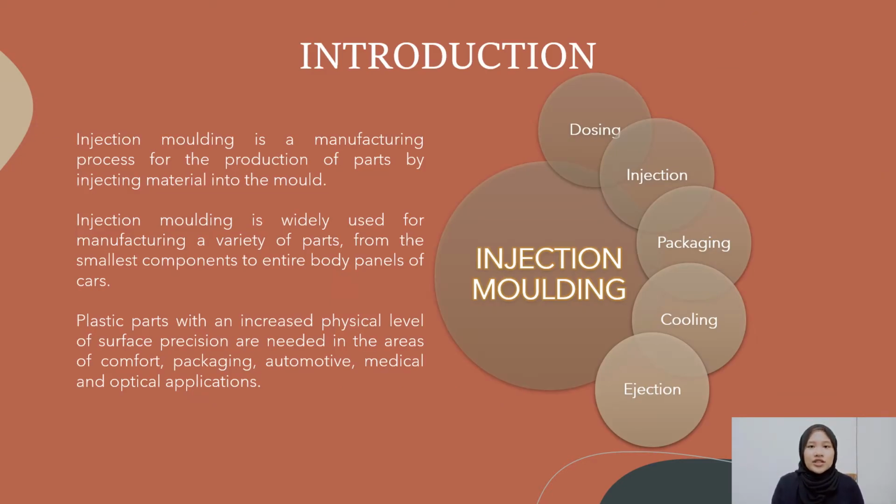What is injection molding? Injection molding is a method to obtain molded parts or products by injecting plastic materials molten by heat into a mold and then cooling and solidifying them. This method is suitable for mass production of products with complicated shapes and also takes a large part in plastic processing.